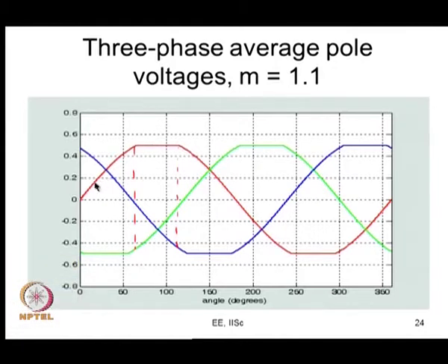You will see pulses on the R phase PWM waveform here, but you will see no pulses here. The top gate device will be continuously on. Similarly, if you look at the R phase PWM pulses, you will see that it is continuously off here. The top device gating signal will be continuously low, and the bottom device gating signal will be continuously high. So, there are pulses here and no pulses here, and that is why it is called pulse dropping. So, this pulse dropping begins.